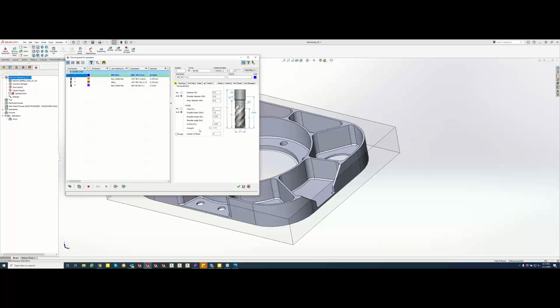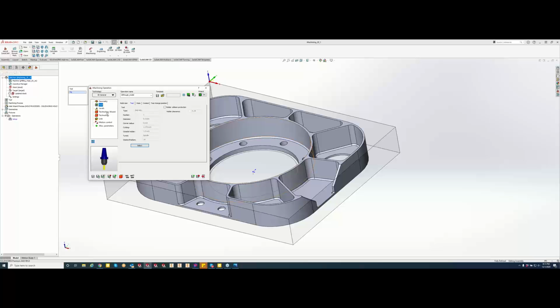You know, it's amazing. So what we can do in here is we also have the iData tab right here. Right now we're using a 5-flute with a 45-degree helix. But let's take a look here and switch it over to a high helix. Even though I'm using this drop down here for the helix angle, you can type the number in there. So let's say we're using a 50-degree. It's going to automatically grab that 50-degree for us, even though it's not a drop down pick. So let's try our 50-degree helix.